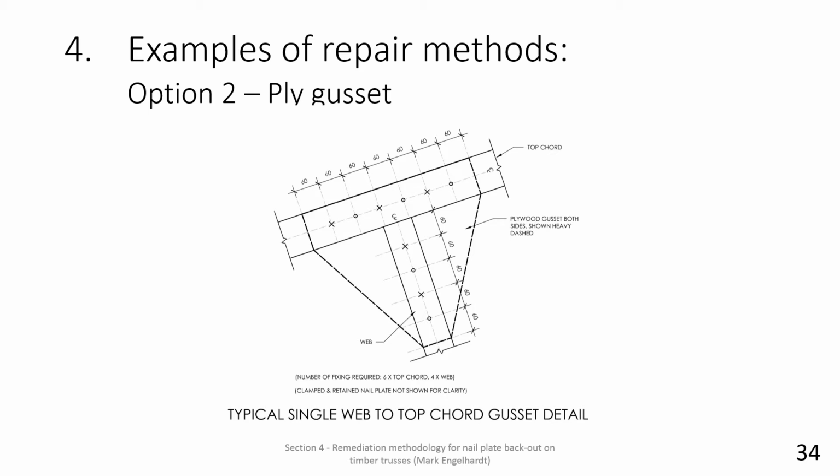Option 2 example, web to top chord typical plywood gusset detail. Once again, it's designed by an engineer and installed by a carpenter using the same method and materials as previously mentioned.